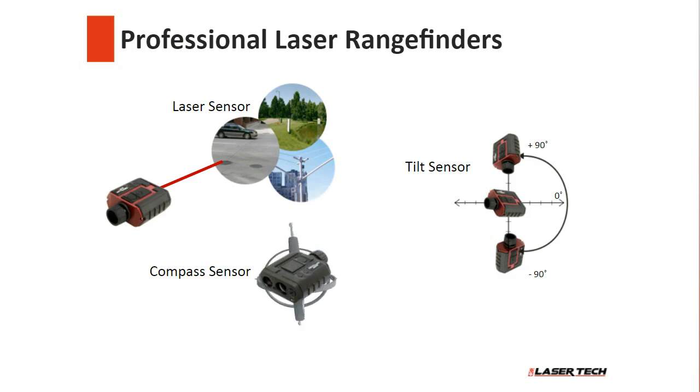Perfect. Thanks, Mike. Really appreciate your expertise here today and just talking about all the tools that you use. We're going to go into a little bit about what lasers are, laser rangefinders. So the Laser Tech here, we focus on pulse technology, AKA reflectorless technology. So we can get a range to almost any object without a need for a reflector. As long as you have a clear line of sight, we can get a measurement to that object.